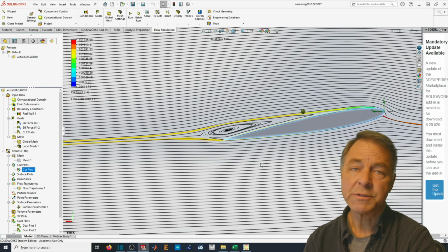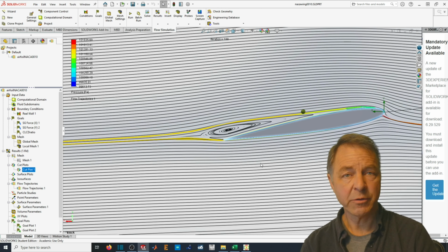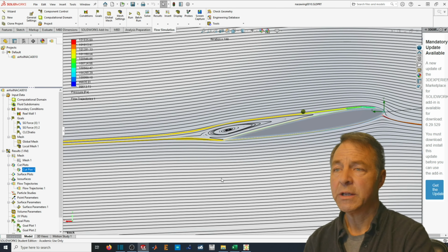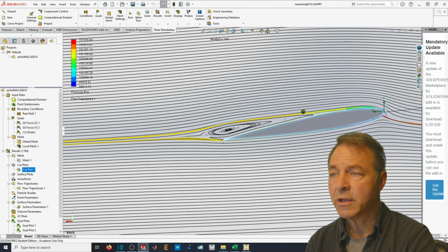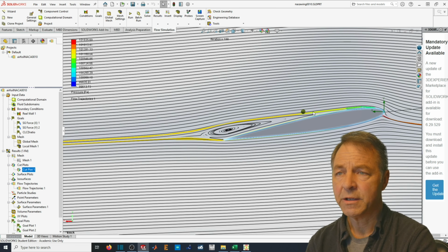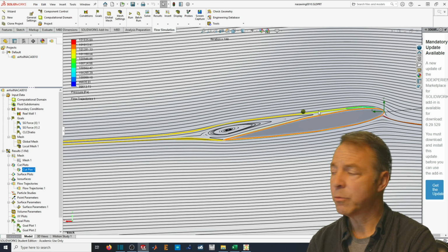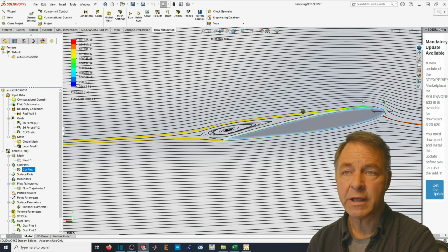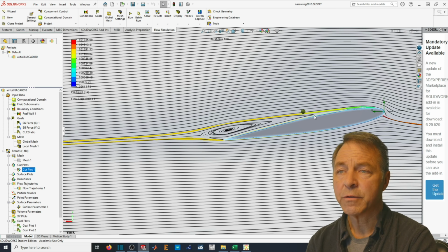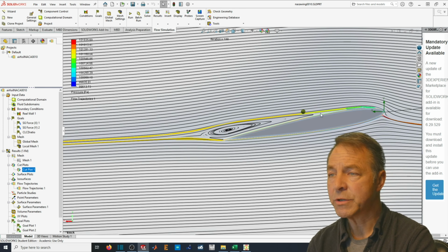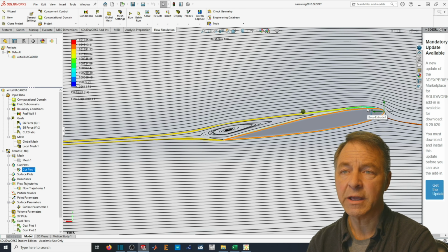And in fact, what we would see is that oscillating up and down of the lift to drag coefficient is essentially this feature, whatever it is, this vortex feature, spinning around and moving, and the separation point that this software is predicting is moving from right around here where my mouse is up and down the surface of the wing. The further that the separation point where this vortex forms goes towards the leading edge, the less lift we have and the more drag.